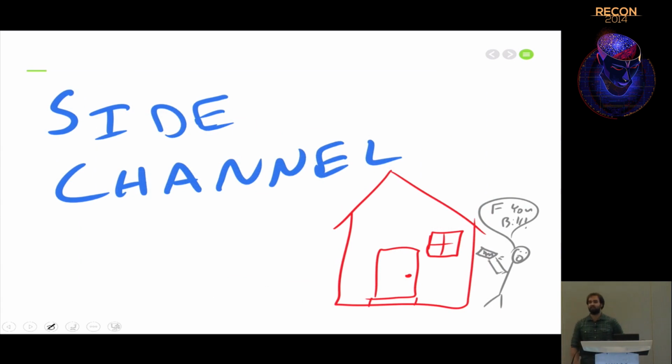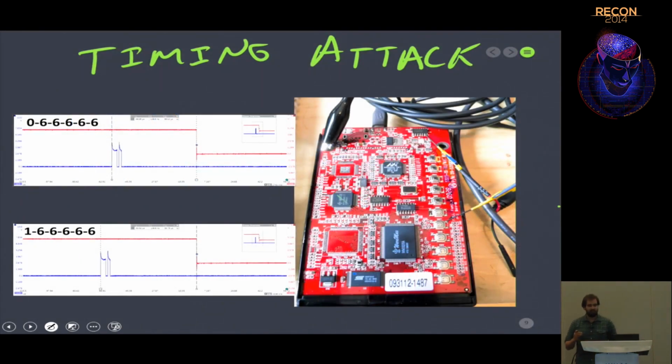So to bring you into this slowly, we can begin with what a side-channel attack is in general. When you say side-channel analysis, it's just something that's not the front door, it's through the window. As an example of this, there's a hard drive that's now end of life, but it has a little pin code on it, and if you put in the wrong pin, it doesn't enumerate properly. So it's pretty cheesy. But how they do the pin check, and you'll see this in lots of stuff, is you enter the 6 digits. After you enter the digits, it just has a while loop that's going through and comparing it. The theory is there should be 1 million combinations of this password. So it's pretty secure. But the problem is, as soon as the while loop fails, it just exits.